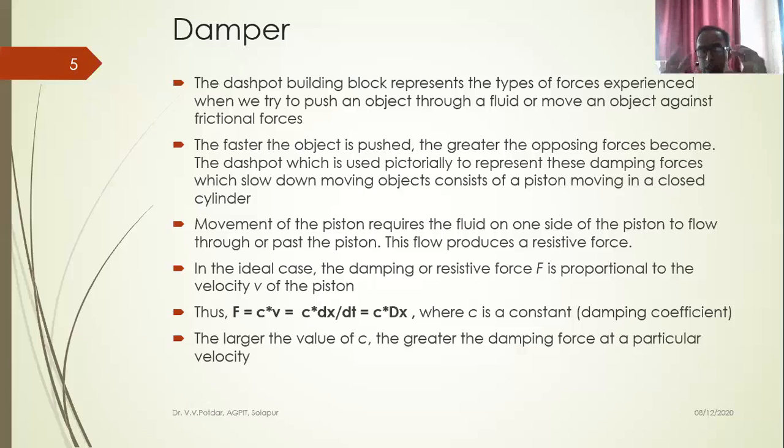We have the mass of the motorcycle and the rider and the pillion rider, that is the mass element, and then we have the springs, or we can have the tires, sponge, cushion, the tire or the rubber-like element which has a stiffness. Those are not actual springs, but those are spring-like elements. And then I have the damper-like element also.